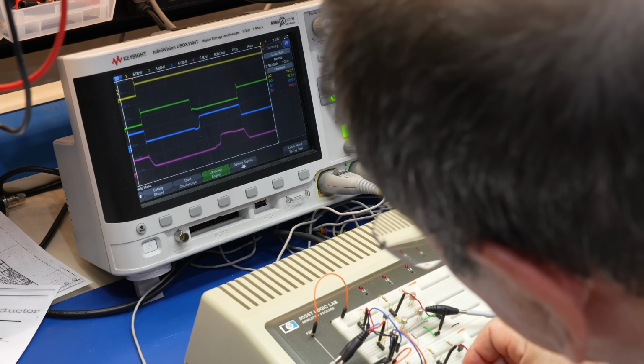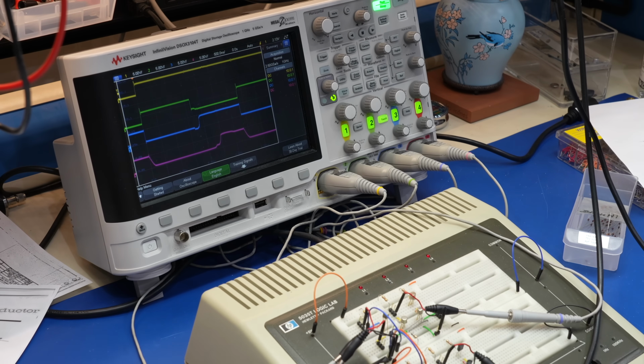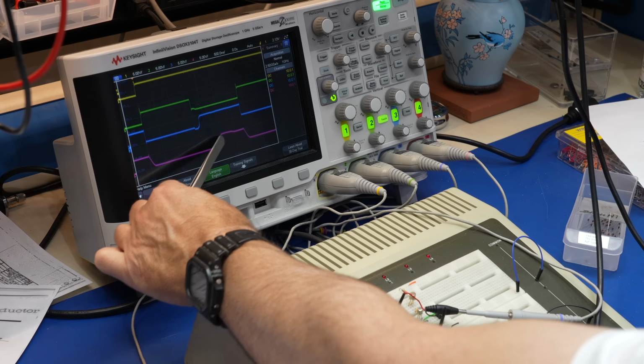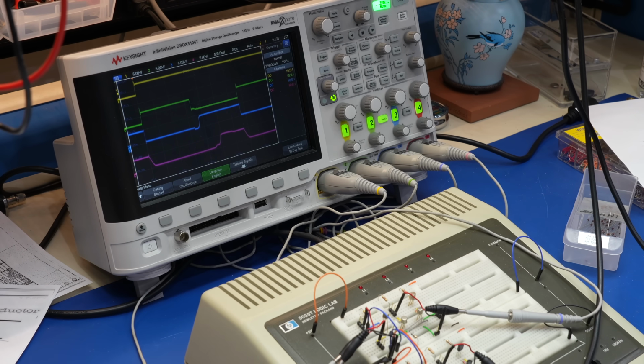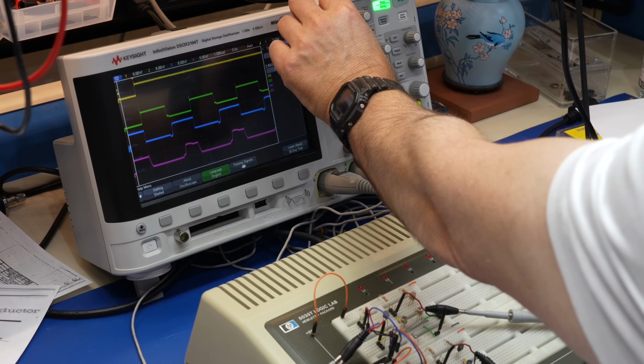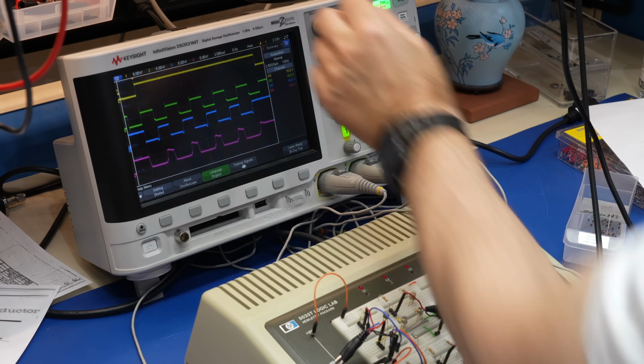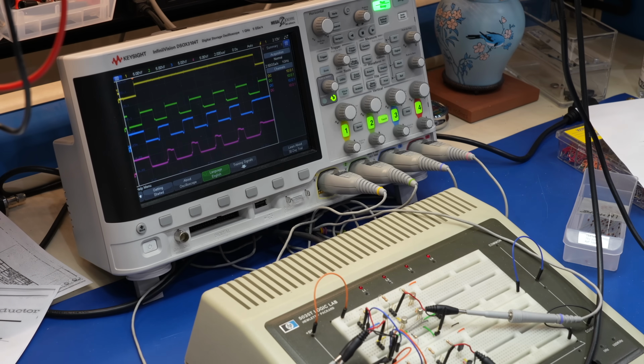There we go. So it fixes the DTL too, but the DTL is hopeless. Q2 takes so long to get out of saturation that it doesn't help if I hasten Q4 getting out of saturation. So now my gate should be way faster. Let's see how fast we can run it.